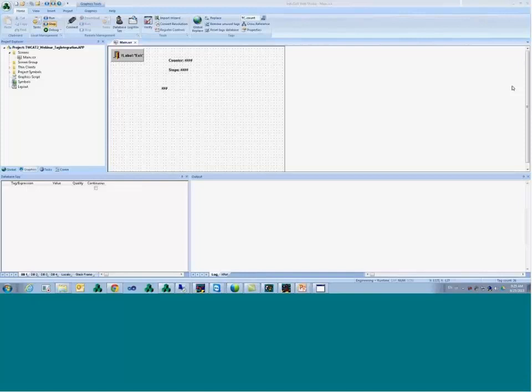So if you're going for any ARM runtime, you can run InduSoft, you can run TwinCAT, but keep in mind that you should do a small application, mostly with native objects. Don't care that much about bitmaps. They are very intensive on the display processing, and then you're going to be fine. So the smaller the device, the smaller the processor, the smaller the application should be as well.